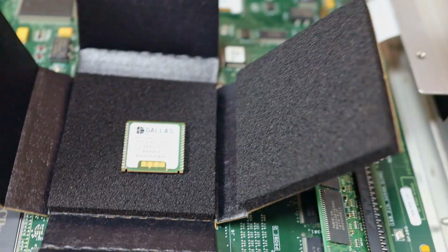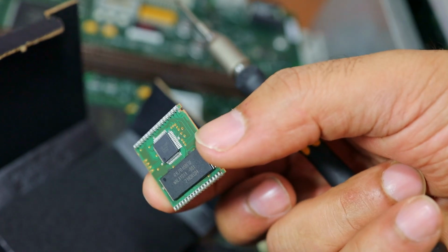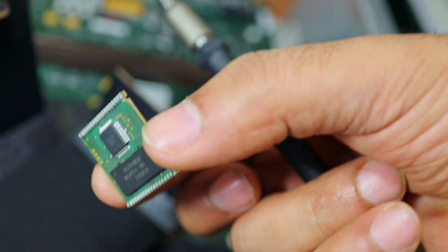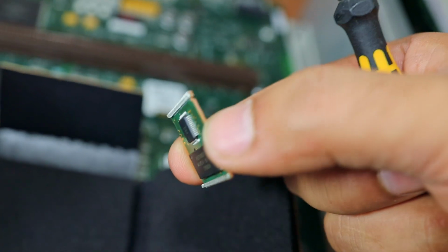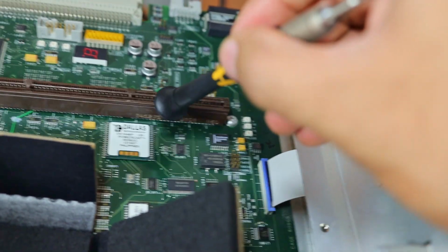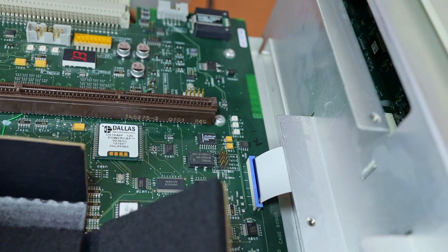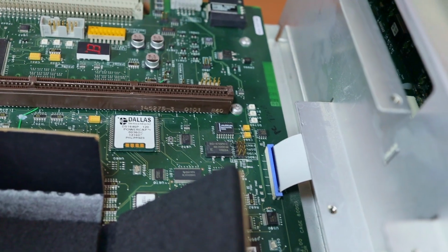So if you want to see the back, this is how it looks. There's a controller and a RAM IC, and there are these pins. This is not completely sitting on the PCB itself. These pins are keeping it a little bit higher, so we will use those pins as a lever here to be able to easily solder. We'll put solder on this side, that side, and lift it on one side, and then lift it from the second side. It should be easy enough to do.